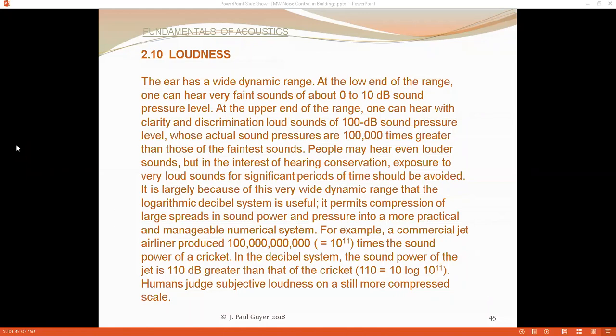If the procedure you're using says sample the sound every 30 seconds, you have your watch and you look down, you read the sound level meter at that instant in time, wait 30 seconds, read the sound level meter again, and then write all of these readings down for the period of time.